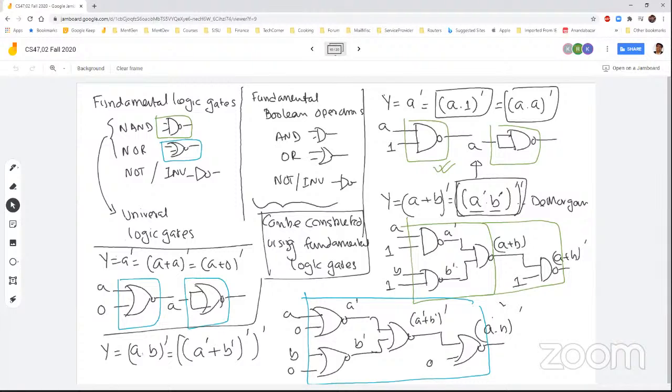You get the faster NAND gate, okay? So you need to see if you can replace the NOR with a NAND to get a better delay, faster performance, so that your circuit can operate electronically in sync with the clock. So this is the main issue there, fundamentally swapping one logic with another.